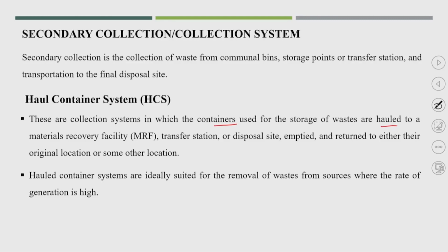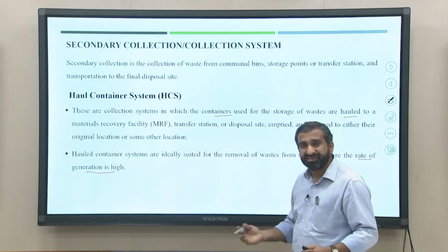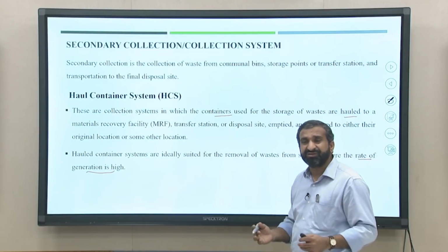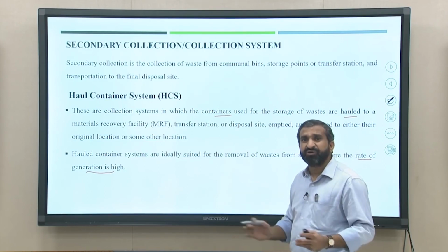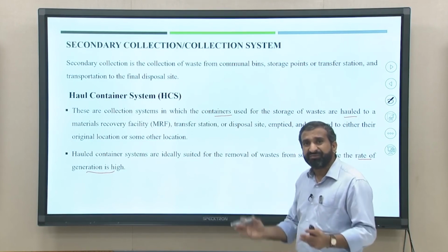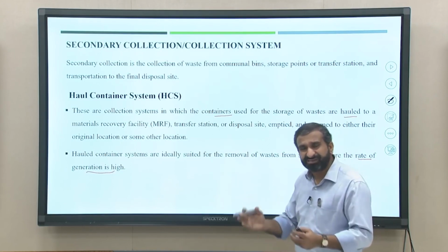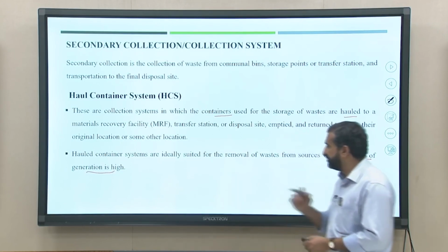That was the haul container system, and ideally this haul container system is highly useful where the rate of waste generation is very high, because when you go for a stationary container system in such cases where waste generation is very high, you will require more manpower, and the time required for hauling that waste is also very large.